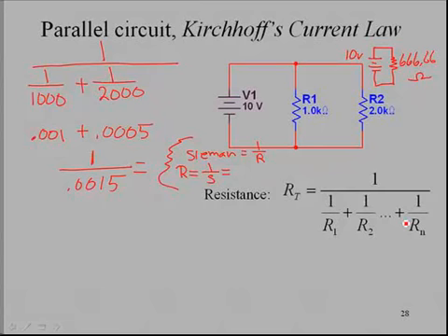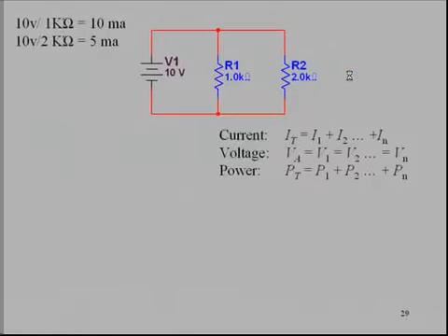To calculate parallel resistance. And remember, the thing that we mentioned in the intuitive relationships was that the parallel resistance will always be smaller than the smallest value of resistance. So in this case, we remember that R1 is the smallest value, 1K, and the parallel resistance was smaller than the smallest value of 1K. Okay, let's go on and do a few more calculations here.